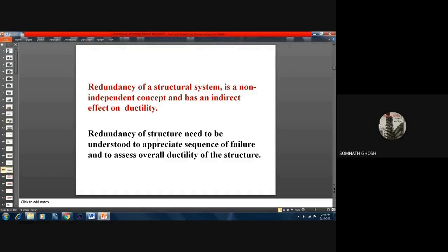Now for a building in different codes, you may find that they are sometimes expecting 3, sometimes 5, or in many structures, even they allow more. Similar kind of expectation applies to individual beams and columns. I mean, for an individual beam also, if you find out the ductility ratio, some codes are expecting 10, some 12, some 15, like that.